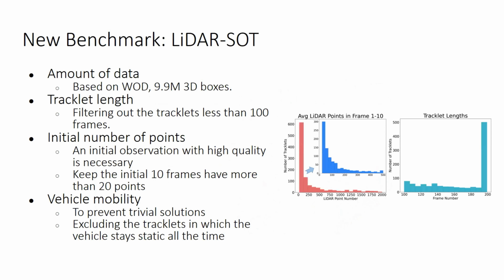To serve this goal, we first built a new benchmark called LiDAR-SOT, based on the Waymo open dataset. The Waymo open dataset has a large amount of data, 9.9 million 3D bounding boxes. Because we're concerned with the single object tracking setting, we filter out all the tracklets with fewer than 100 frames and only keep those with frame numbers larger than 100.